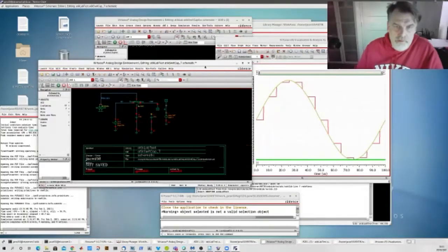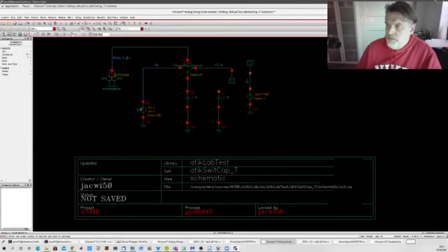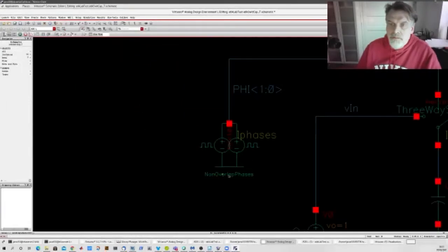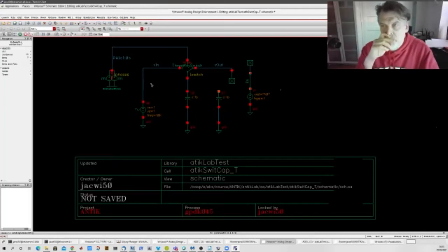So in the lab for this course, I have created some help circuits. There is one generator that creates non-overlapping clock phases that will be helpful when you control the switches. So we will get two clock phases, one on and one off. They can't overlap because then I would turn on the switches at the same time, charge would be shared, and I would destroy the operation. So I really have to distinctly move my switch up and be in the position between the two states for a short period of time, just to avoid any shorts.